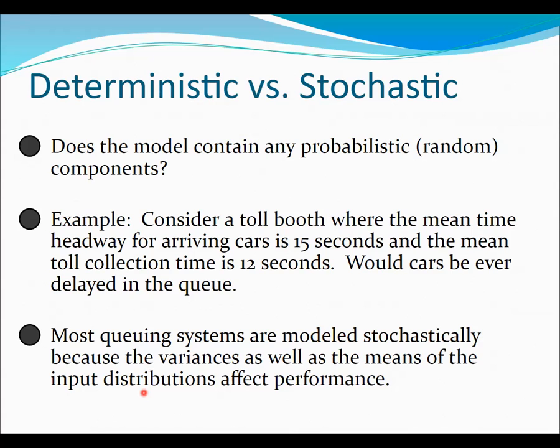Or you could, in VISSIM for example, if you have 240 vehicles per hour originating from a point, you let VISSIM know that in every run, you pull the number of cars that are actually going to leave from a distribution that has an average of 240 and a certain variance within that. So basically a normal distribution around the average of 240. And then sometimes, depending upon the seed number that you're using, VISSIM will have 250 cars come out of that. Sometimes it will have only 230, or some number in between.